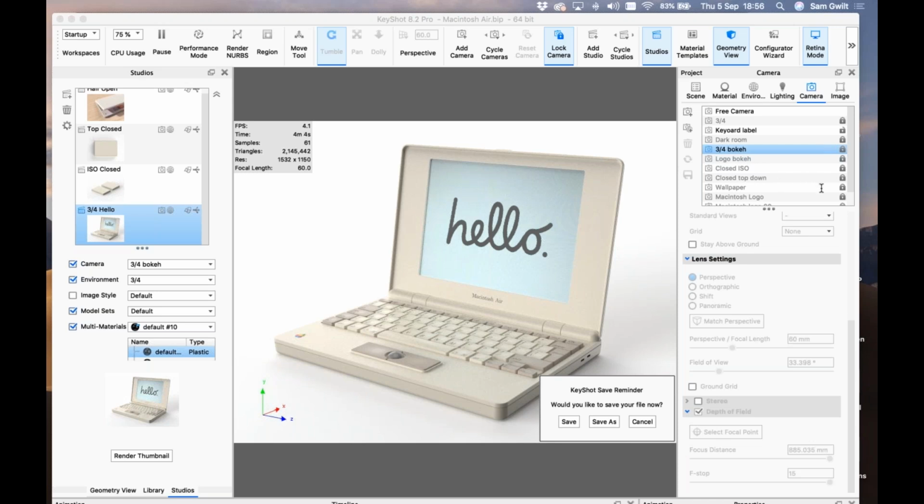What should I keep in mind when doing ID modeling for a computer? Made one on the website. Yeah, so like I said, all the draft angles, make sure you can fit the components in, make sure you can bring it into realistic proportions as soon as you can in the design process. That's going to really help you out later on.